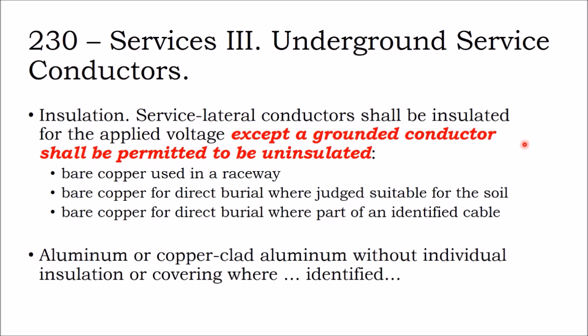If I have a feeder cable or a service cable that is rated for external environments, for weather resistance, for wet conditions, and I want to run it over a rooftop, my inspector won't require me to use PV wire. They'll say, well, we use USE-2 wire, and I see you're using USE-2 wire, underground service entrance wire, so we'll permit you to do it.